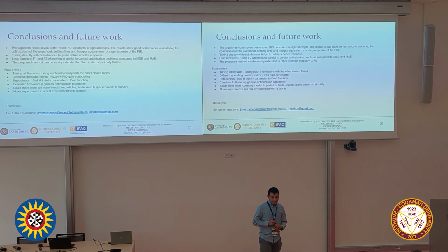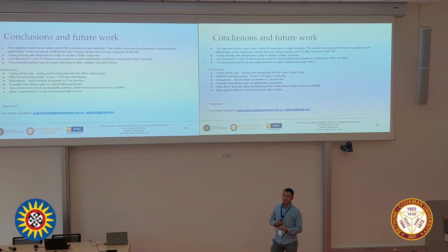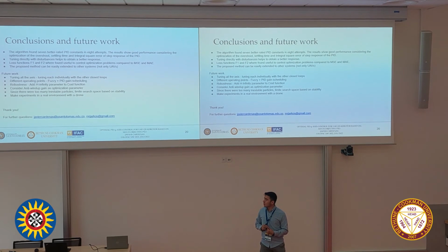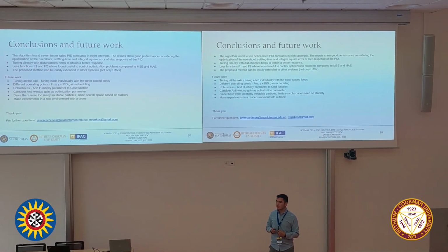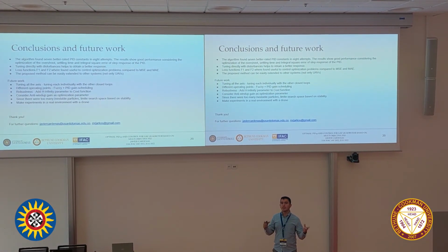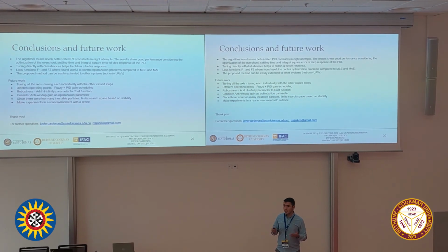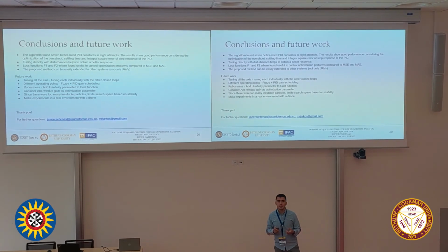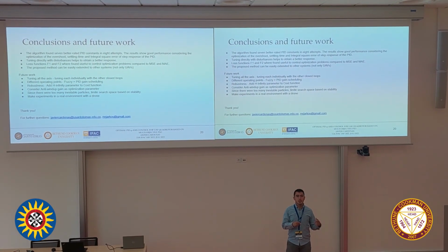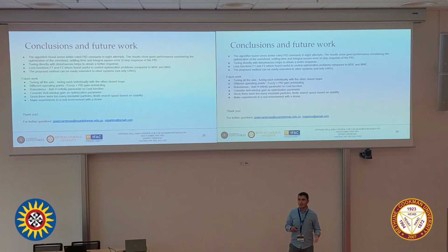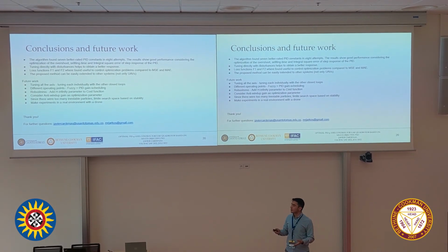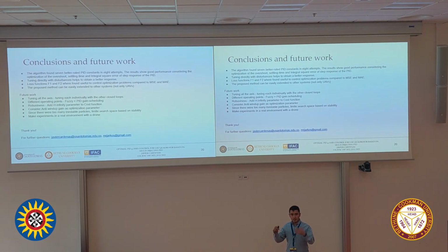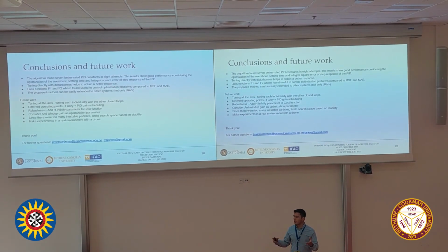Yeah, this is one of the biggest problems of this system. There are some proposed solutions. For the nonlinear model, this time we are only tuning for one operating point, but we can run this algorithm for many operating points, and then I don't know, we can use gain scheduling or fuzzy to mix all the systems for a nonlinear model.